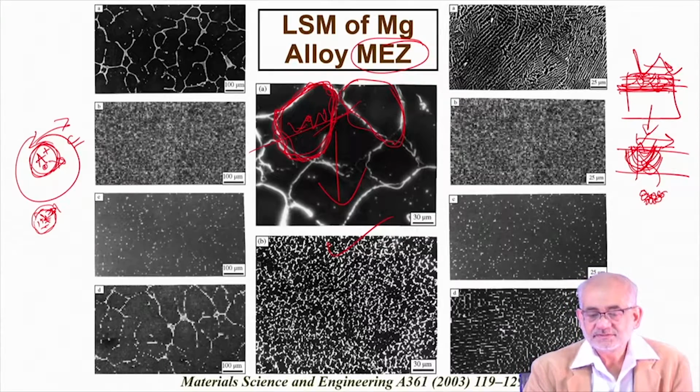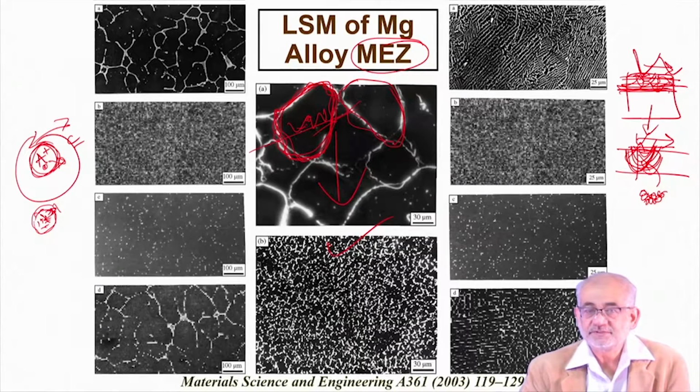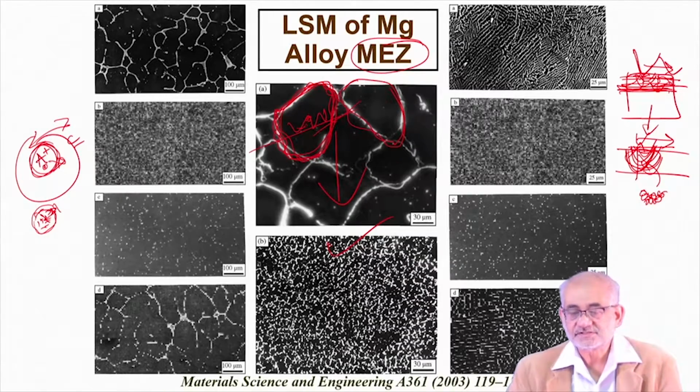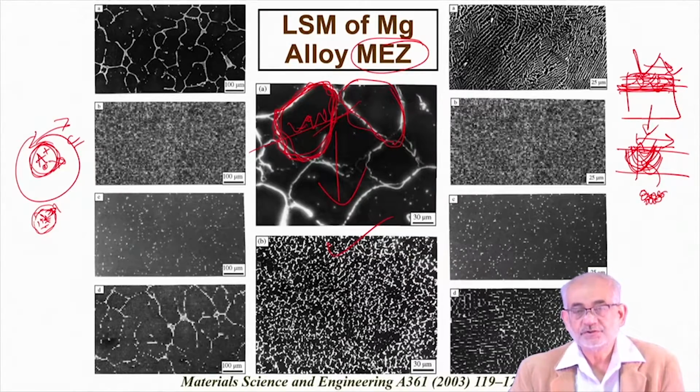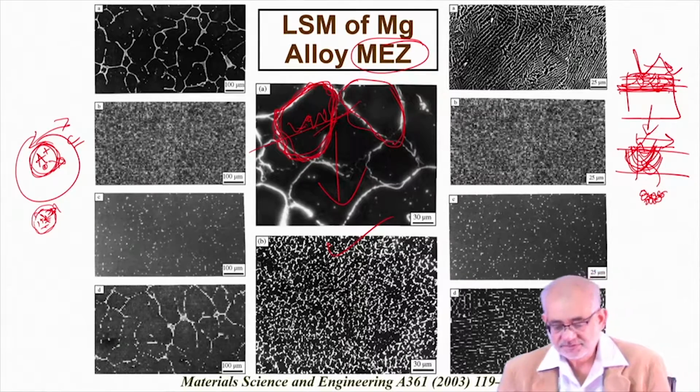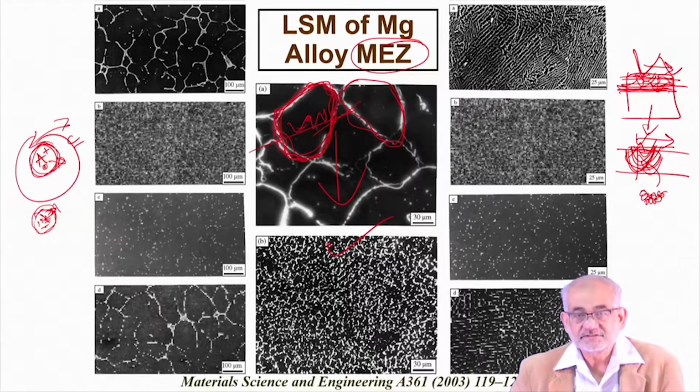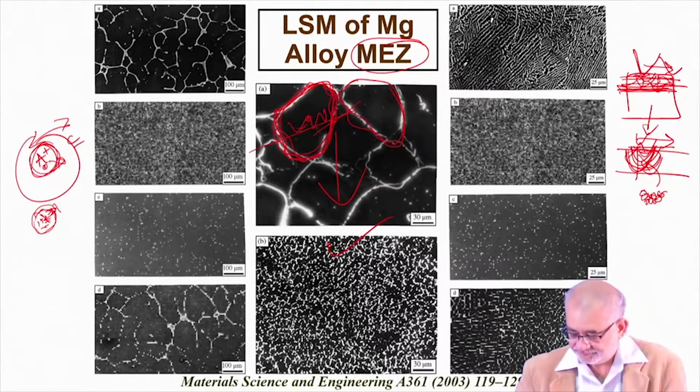And this strategy is applicable not just in magnesium alloys bearing certain rare earth elements, it can be true for all other non-ferrous systems which can be given very limited surface melting up to a certain depth, leading to ultrafine grain refinement, which in turn will give you very high wear resistance and also corrosion resistance. I mean, this is not universally possible, but certainly possible and can be extended to very many non-ferrous systems, where martensitic transformation is not a possibility.